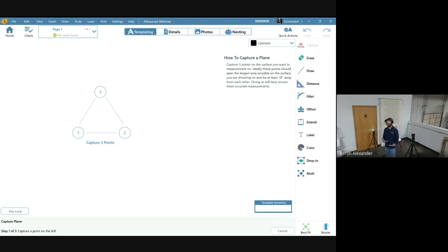Especially, I'm going to focus more on not just the face surround of a fireplace per se, but we're going to get more into mitered edges and mitered returns here, how we're going to capture those, how we're going to square things up and plumb edges up in space, to make sure that when we install these miters and these side pieces, the returns in relation to the face, those miters are going to line up and everything.